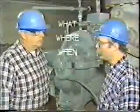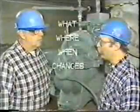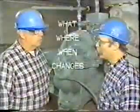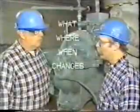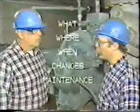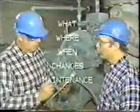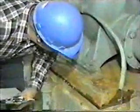The leakage has steadily increased since then. The operator tried tightening down the packing gland, but that didn't seem to make much difference. And at that point, he reported the problem. The answer to the last question Gene asked was that the packing had been changed not long ago. Gene is going to go right to work with his operational check.